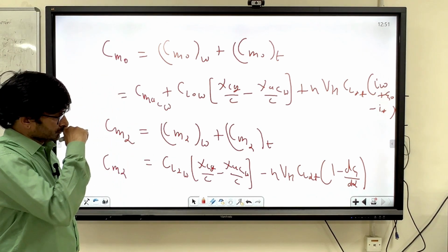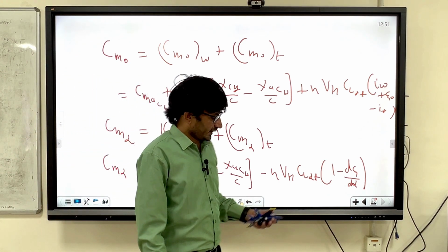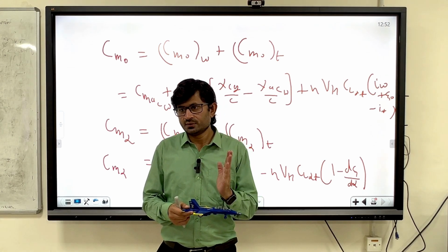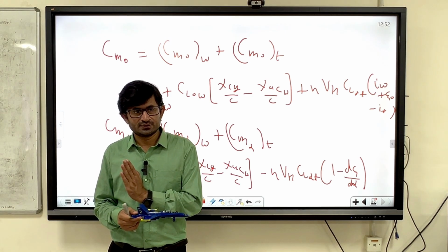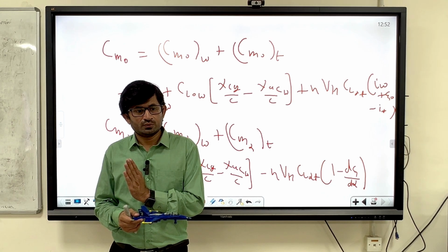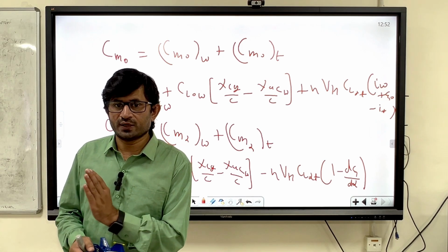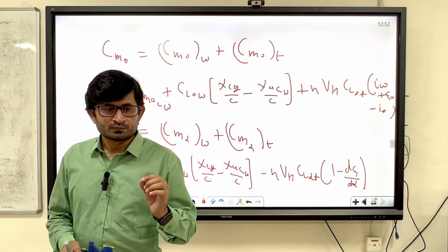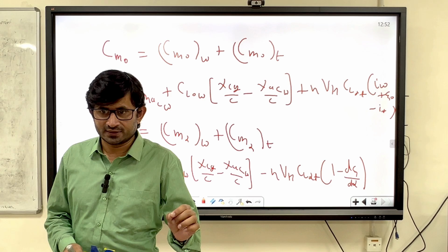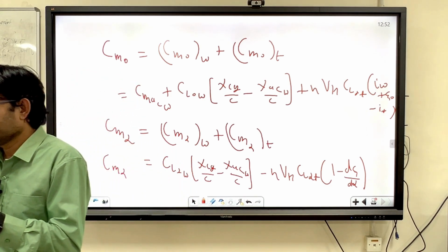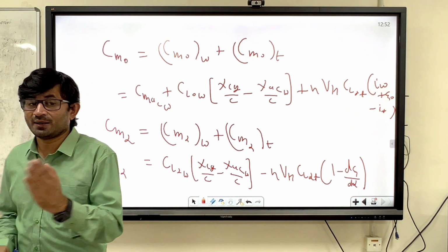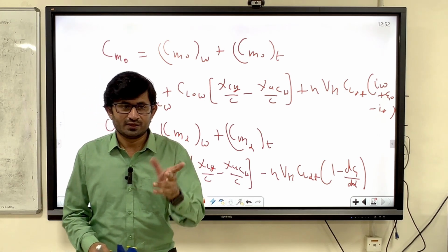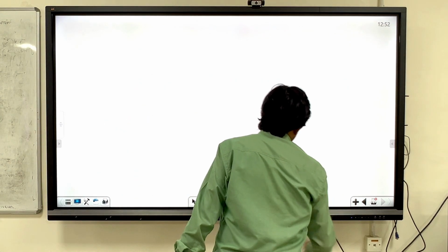Okay, now you calculate this. I already told you that when you put the tail, you are taking the aerodynamic center behind the CG. So after placing the tail, we have to find out where the resultant aerodynamic center is located. When you consider only the wing, it is called the aerodynamic center, and when you consider the complete aircraft, it is the neutral point. So what will be the neutral point? You took the aerodynamic center somewhere by placing the tail, but we should also know the distance to where it went. Now we will find the expression of the neutral point.